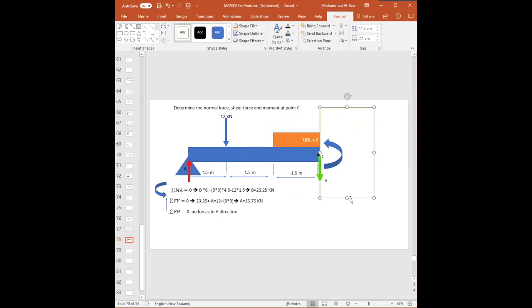And therefore, when I cut, I replace whatever I have at that point with a shear force called V and a moment M. So I need to type that the moment is called M. Because that's what we're asking you, to find M and the shear force. If you have any questions here, guys, please ask me. Why is it going anti-clockwise? All right, good question. Because if you look at the direction of the balance, how can I explain it in an easy way?